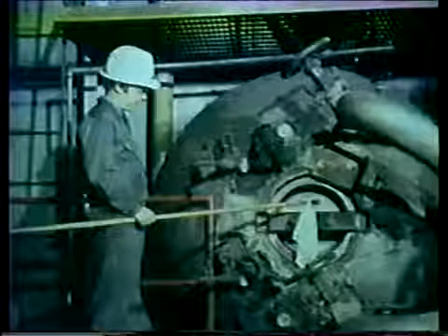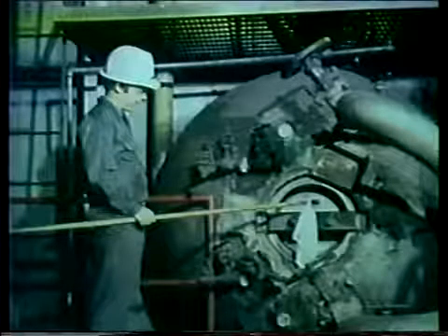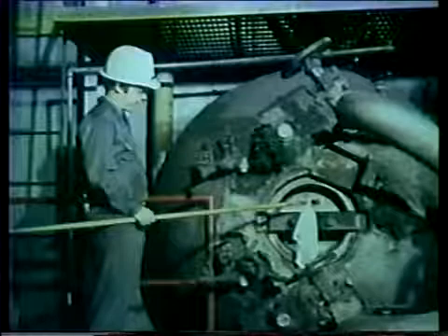Be cautious when checking the covers for leaks at operating pressure. Steam is invisible. When you see steam, what you're really seeing are tiny droplets of water that look like a white vapor. These are droplets that have condensed from the steam. However, if the boiler temperature is high enough, condensation won't take place until the steam is far away from the actual leak. If high temperature steam is leaking past the seal, you won't see it. To avoid burning yourself when making these inspections, check the covers with a rag attached to the end of a stick. A steam leak will make the rag move around.